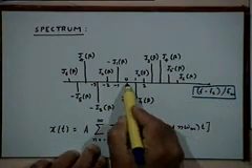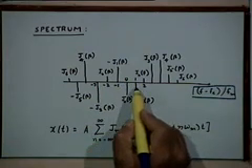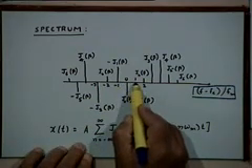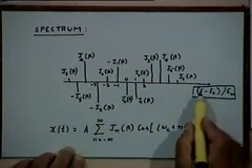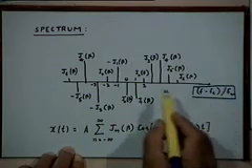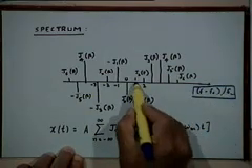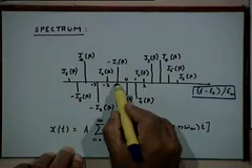So when I say this point being 0, that means F is equal to Fc here. So for this point we are looking at the spectral component at the point where the deviation is Fm, F minus Fc is equal to Fm. So basically this component denotes Fc plus Fm and this component denotes Fc minus Fm.